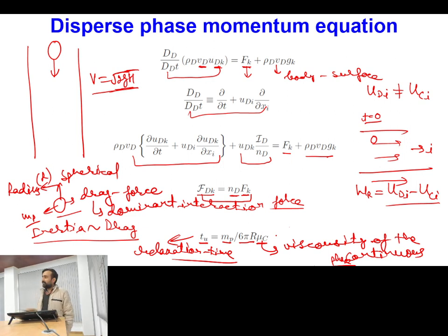By using that formulation of drag force and the inertia of the particle, which is nothing but mass into acceleration, so m into d square r by dt square, I have not calculated it exactly, but we have just done an order of magnitude balance between the two components. Then we will be getting this as our relaxation time. Is this one clear?